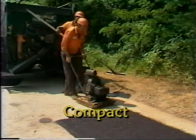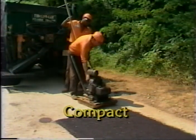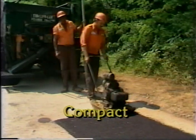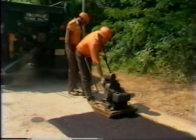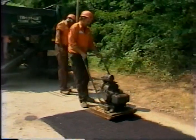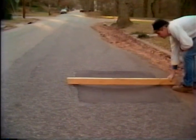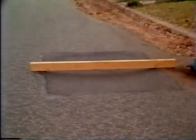Compact the material as soon as it has been placed. This is the sixth step and one of the most important. If the material gets cold, it cannot be compacted. Poor compaction will result in depression under traffic and ultimate failure of the patch.